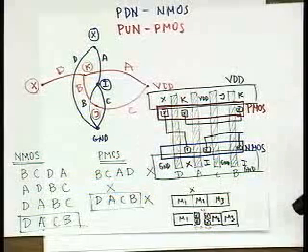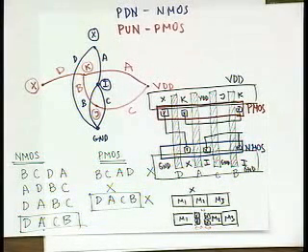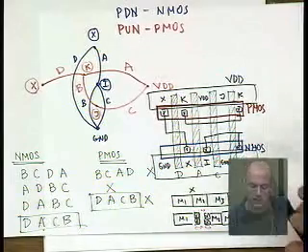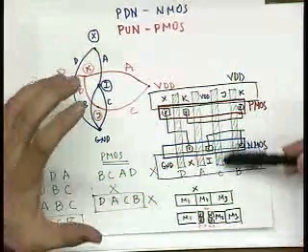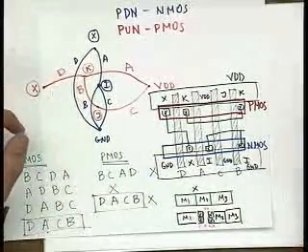Everybody clear? One more question. The example in here always assumes the same W for all NMOS and for all PMOS. Is that common practice, or do people want to scale those so that they're different? That's a great question. We obviously assume the same W here because we had the same width of this diffusion stripe, and that's correct.